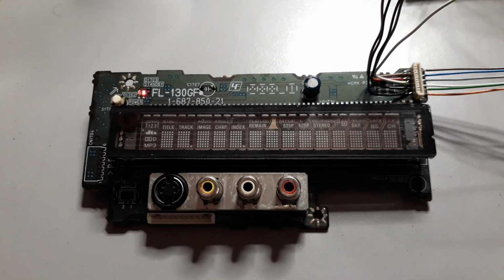Of course, we have a GND and a plus 5 volts DC for power supply, and the GND must also be used to create the reference for the DC-DC converters and the Arduino or another MCU you use. With these small steps, we can easily bring our panel to life.